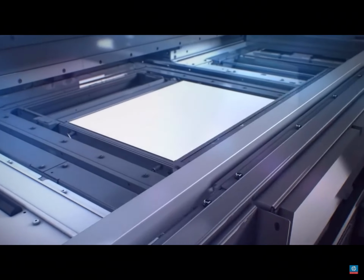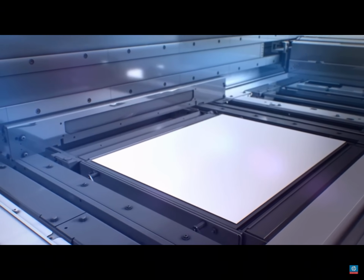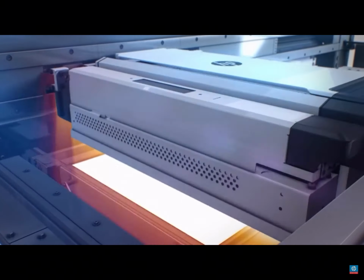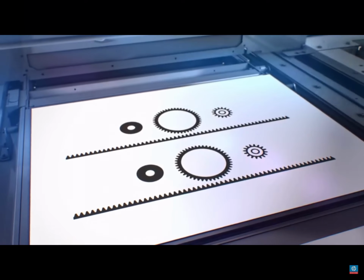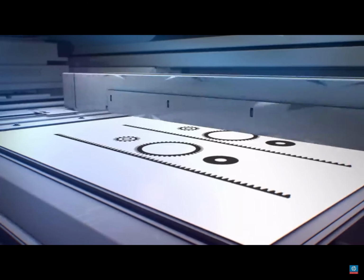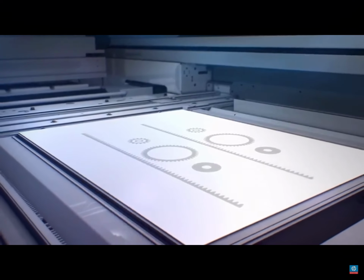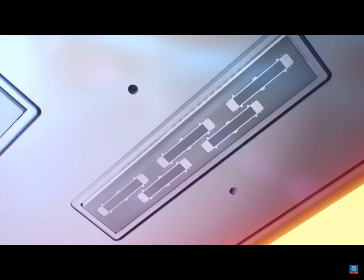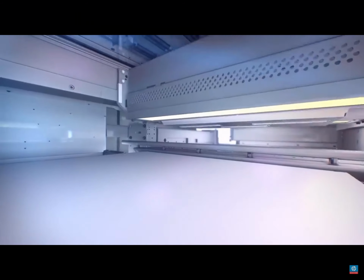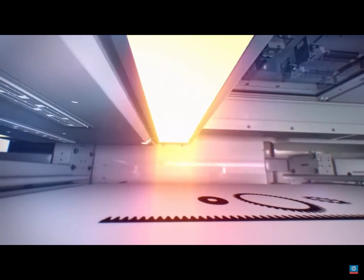The process begins by applying a layer of material in a work area. In the opposite direction, in one continuous pass, we print fusing and detailing agents across the full working area. This pass combines the printing with the fusing energy, and the process is then completed. HP's proprietary architecture is capable of printing 30 million drops per second along every single inch of bed width, enabling extreme precision and dimensional accuracy.